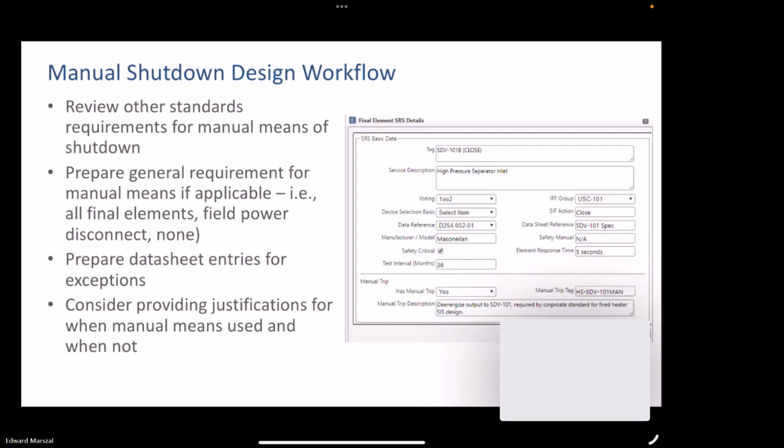Okay, does it have limitations of pipe size to set a manual shutdown valve? Pipe size, manual shutdown valve. I'm not aware of any standard that sets the need for a manual shutdown switch based on the pipe size. The need for a manual shutdown switch is almost always based on what is the application.